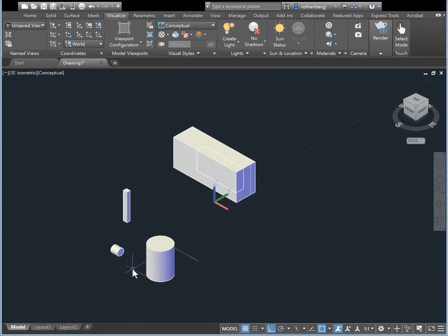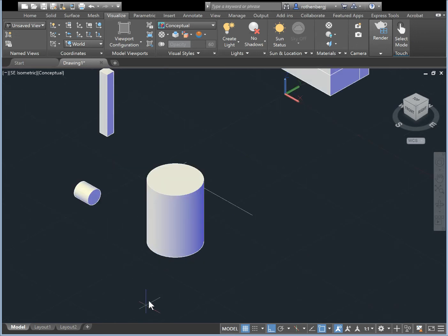So these next 3 pieces are going to be a little more difficult to move, as they are not straightforward, as in just going into a corner. They are offset a little bit. So we're going to start with this large cylinder here. The center of it is 1 3/8 from the left face. So we'll be drawing a line.